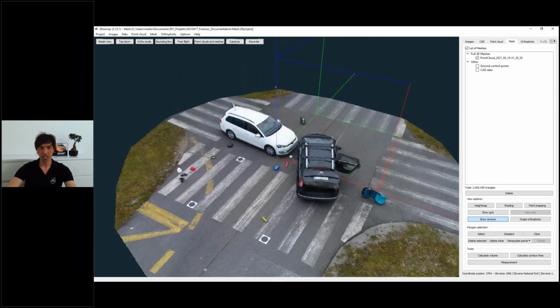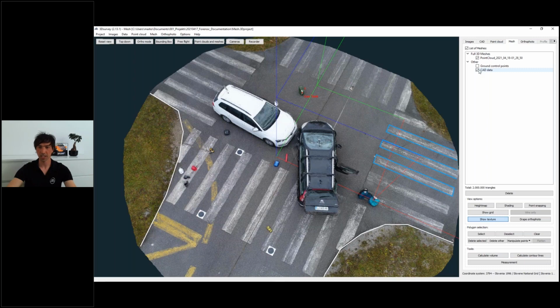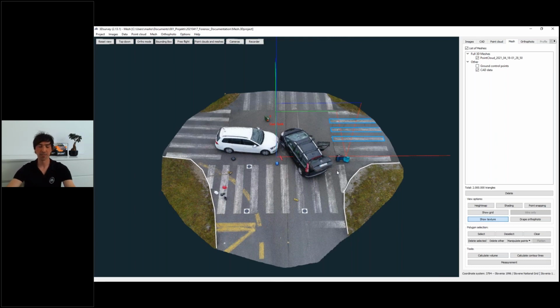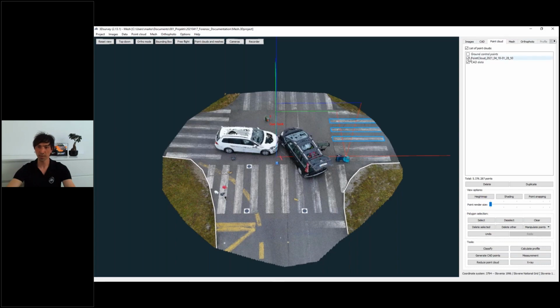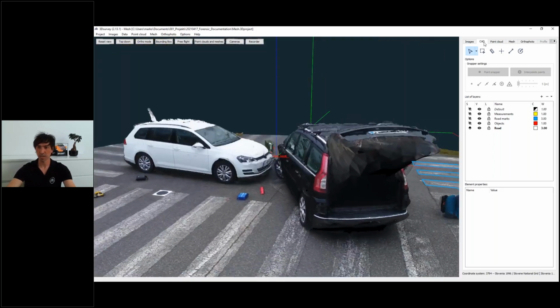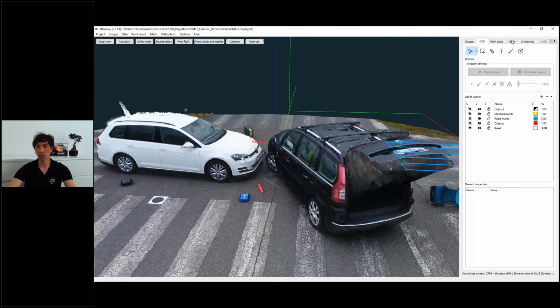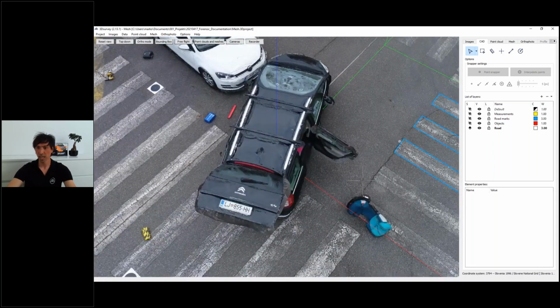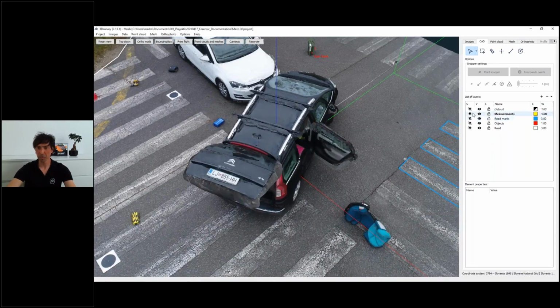And then in addition, we have here some CAD drawings. The easiest way to draw CAD lines, if you need to extract actually out the vector data, is to draw on mesh. That's why you can go to point cloud tab, turn off the point cloud, that you will have just mesh in a CAD tab, okay? Because in a CAD tab, you actually see everything what's turned on in other tabs, okay? And right now I have just a simple texture 3D mesh, and if I like to measure something, here is my layer system. I can add new layers, anything like that. I can select my colors,